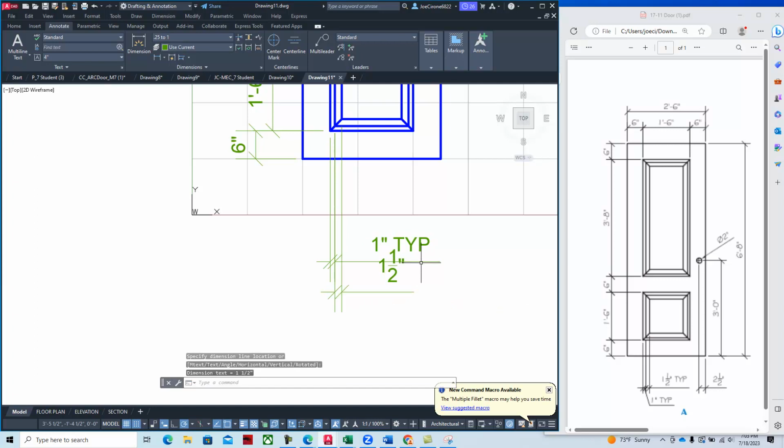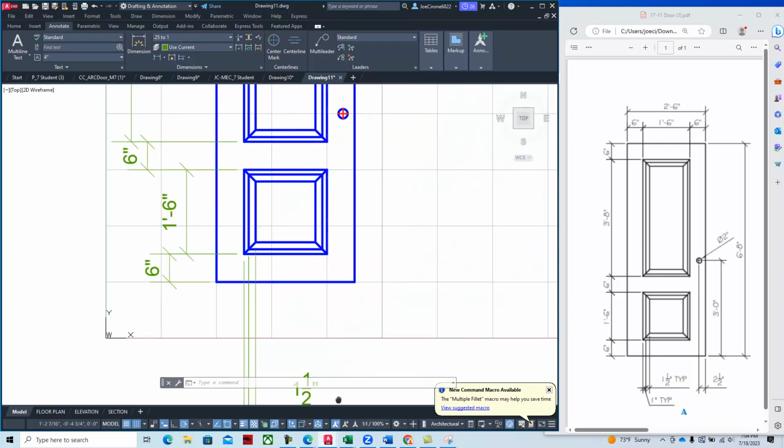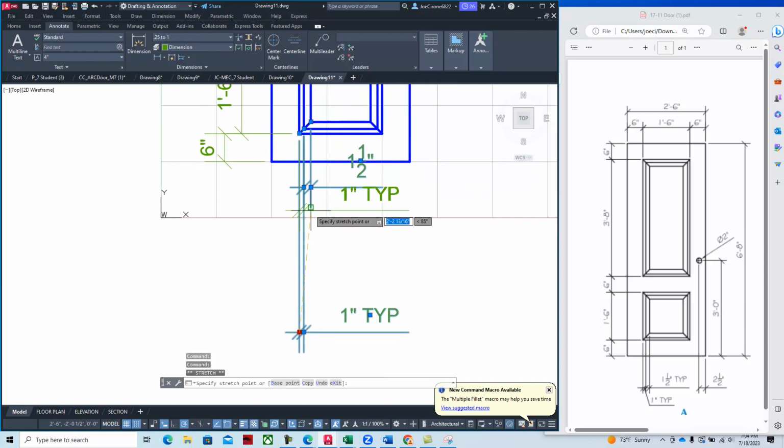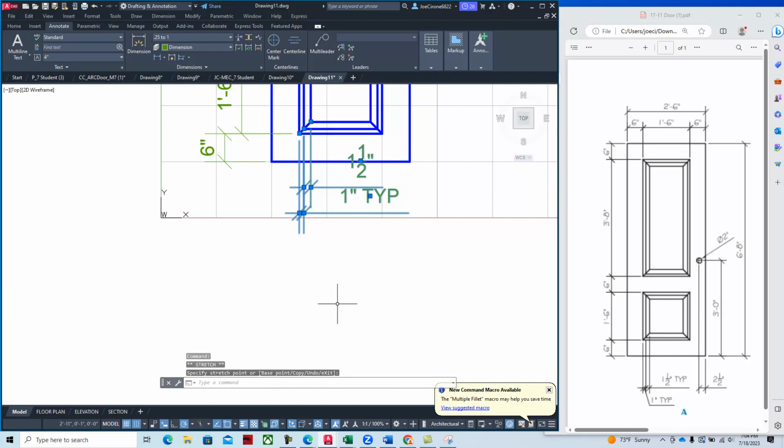And then these are kind of in reverse order if we want to have drawings that don't have overlapping dimension extension lines. These are called dimension extension lines, and the idea is that you avoid crossing over them when possible. Alright, 2.5 inches from the edge. Let's dimension how to get to the knob. We're going to bring this up a little bit along with this one. Hit escape.